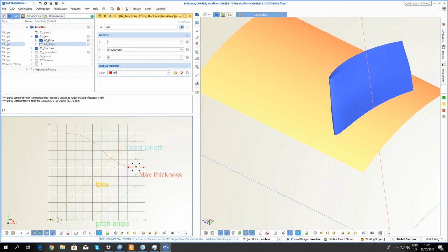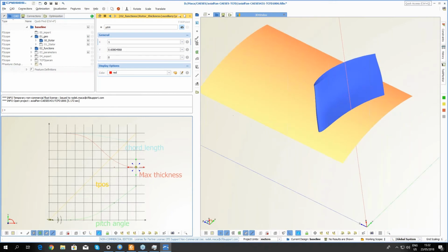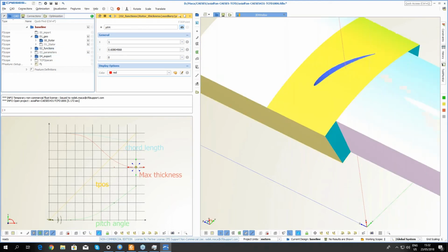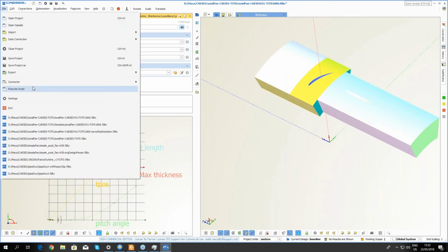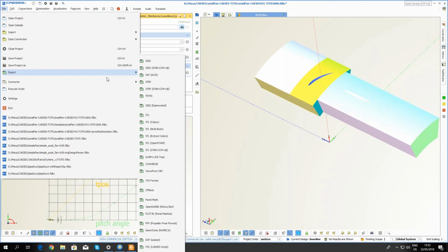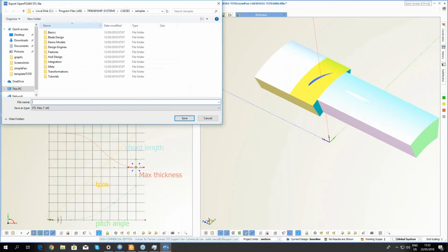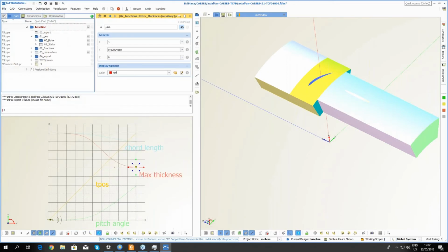So in this case, you can model and create the CAD geometry for almost any shape, and then everything is prepared for the export. So this export, I can easily export just for my CFD setup. Here, just export. There are many export types. For us, we need this OpenFOAM STL output, so we can save it, and then there is time for a CFD setup.